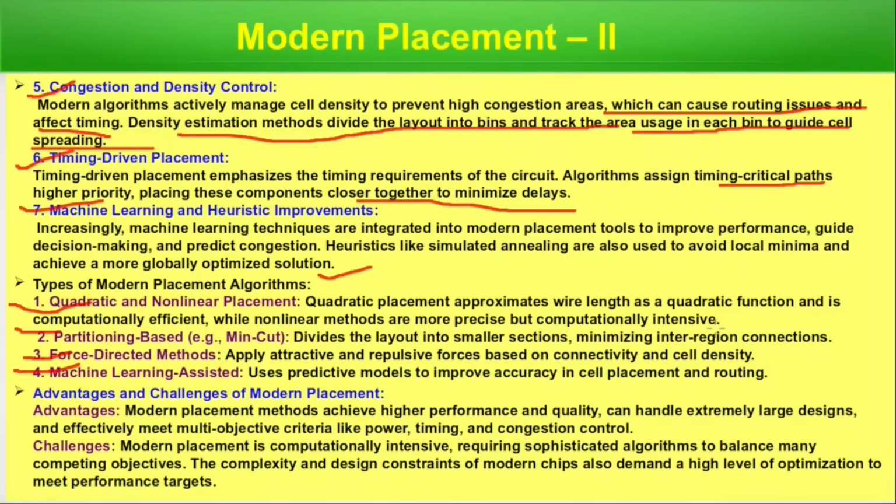Advantages and challenges of modern placement. Modern placement methods achieve higher performance and quality, can handle extremely large designs, and effectively meet multi-objective criteria like power, timing, and congestion control. And challenges: modern placement is computationally intensive, requiring sophisticated algorithms to balance many competing objectives.